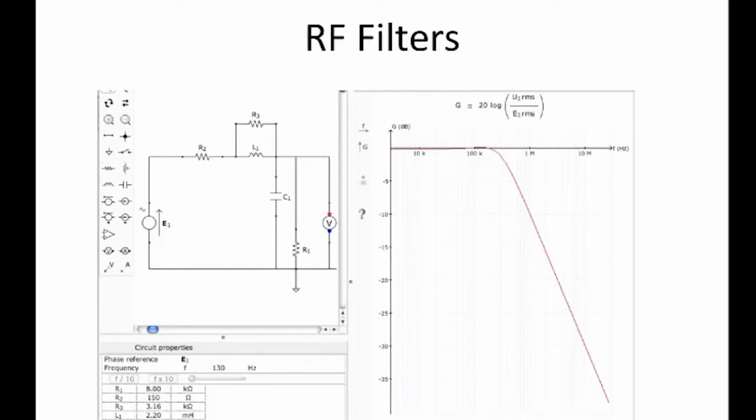Next slide. So here is an example of a circuit which is designed to help filter out RF at the input to a microphone preamplifier. This one has both an inductor and a capacitor, giving a two-pole filter. Sort of, with that resistor across there. Anyways,